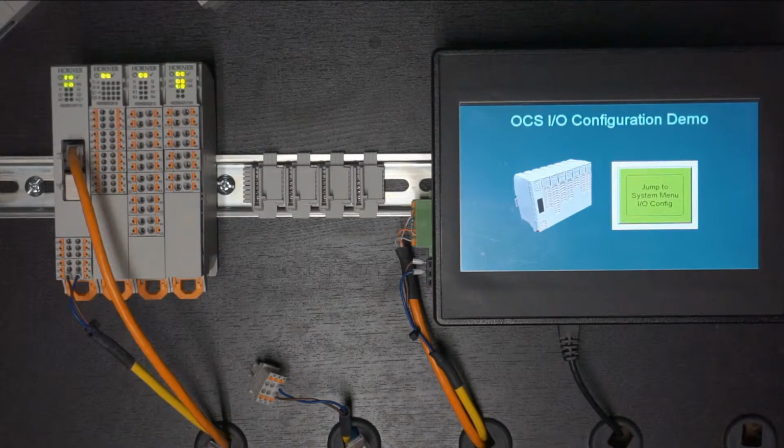Look at that. Okay, so it took a few extra seconds to work everything out, but it was able to automatically find that new base, determine that everything was normal except there was a new base connected, swap out the UUID and its memory table of the OCS, and we're back up and running again. Okay, so that's all there is to swapping out a CNX base without having to open Cscape or do anything else.